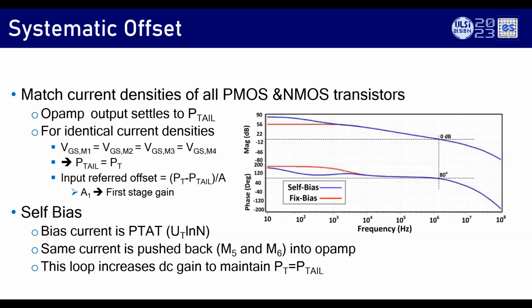So if you want to design an operational amplifier with a higher UGB and higher DC gain, this is one technique anyone can use. Put in a self bias for increasing the DC gain, pump more current in the first stage to get the UGB, and you get both.